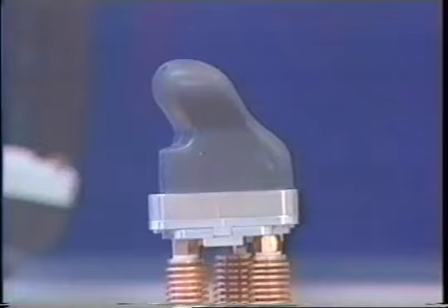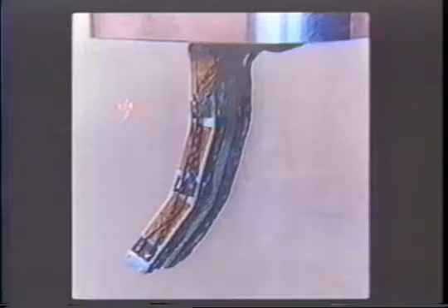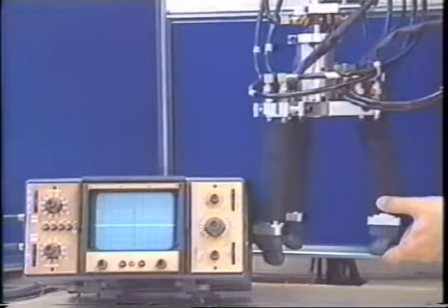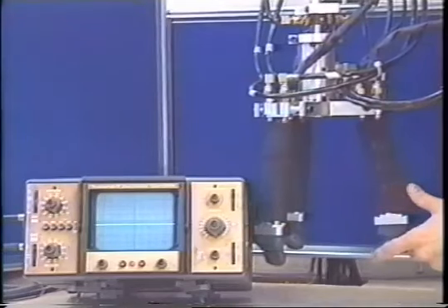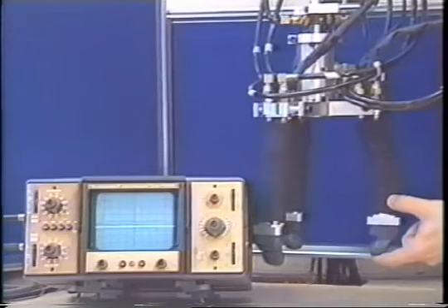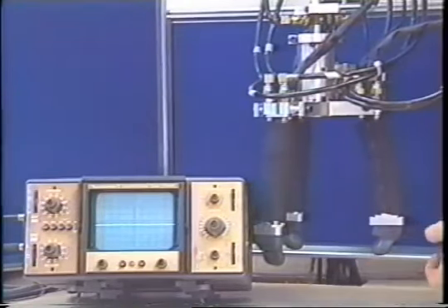At each fingertip, force and slip contact sensors are embedded within a silicon elastomer. The sensors are mounted on an aluminium skeleton with an O-ring sealed 50-way push-fit connector. To minimize changing ambient pressure effects, force sensing uses strain gauges arranged on the skeleton. Redundancy allows sensor fusion to better estimate force magnitude and orientation.